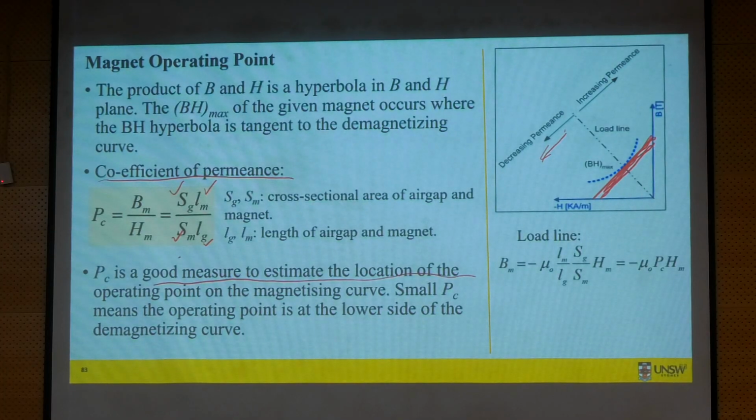Yes, that's what you would like. Here you have less demagnetization risk as well as a higher B value. The higher the B value, the higher the air gap flux density it's possible to get. Ultimately, air gap flux is what will give you the torque, right? So when you are designing the motor, your main objective is to get the highest torque out of it. So higher flux density at the air gap is better. Okay, any other discussion?